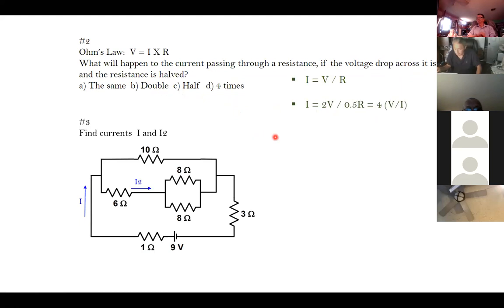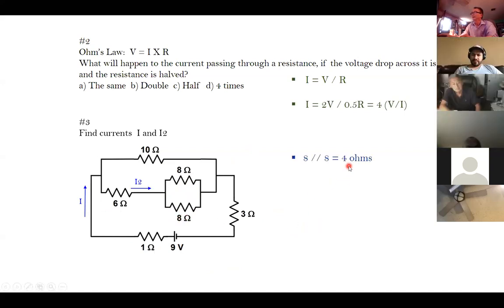Okay, now on that one, I will not make you stay for the calculation, it takes a while. However, I want to explain the way we can solve the problem. The first thing you look into the circuitry: 8 ohm and 8 ohm in parallel. You can combine them: 8 times 8 divided by 8 plus 8. That's 4 ohm, no? That's why you get 4 ohm.